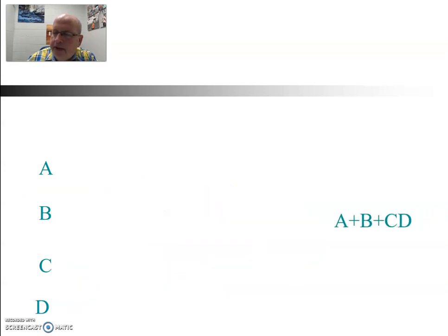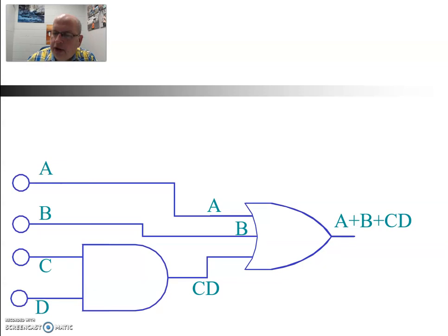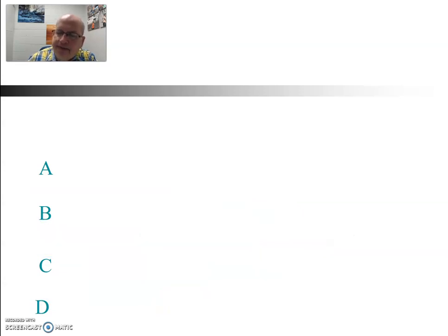Here's another one, A plus B plus CD. Again, A plus B can be on one input, or we can actually use a third input on the OR gate. Either way, we can implement that. So it's just an alternative way of implementing that expression.